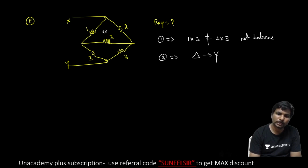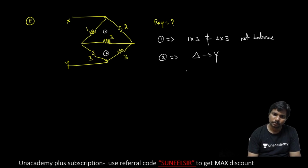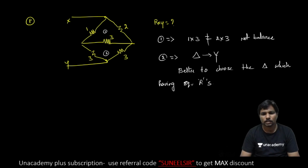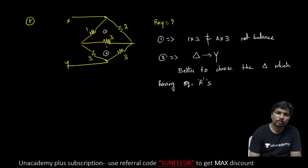Whenever it is not balanced, the second step is to convert delta to star. Here we have one delta, and here another delta. It is better to choose the delta having equal resistances. The upper delta has 1, the lower delta has 2. In the lower delta we have equal resistors, so I want to convert this lower delta into star.